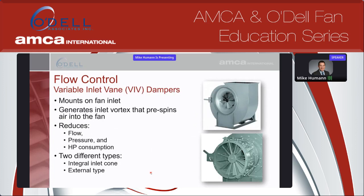So on the inlet side, you have a couple of options. You have a variable inlet vane damper, and on the right-hand side, you'll see the internal one, which is mounted in the inlet cone or venturi. And then you also see an externally mounted damper. The internally mounted one, the upper damper on the right-hand side, has more leakage. It's not as inherently robust, so it's not meant for more difficult or demanding applications. But they do have the same effect.